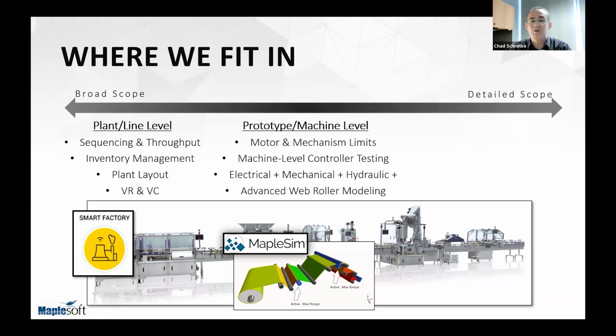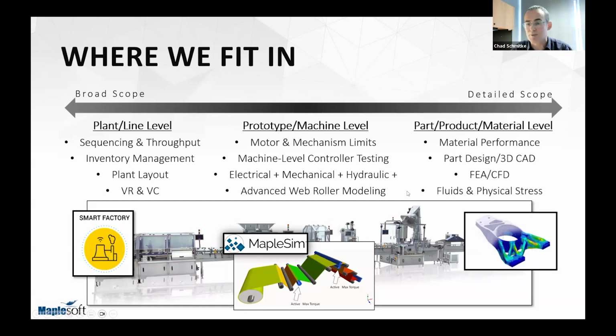These are the questions you ask of a system-level model. And then, for completeness, we can add the detailed scope, which is when we're looking at parts. Often people talk about the actual deflection or the twist in these kinds of parts, and that's a more detailed scope. You could theoretically use FEA to model a much larger portion of the system, but the time and effort involved usually doesn't make it worthwhile.